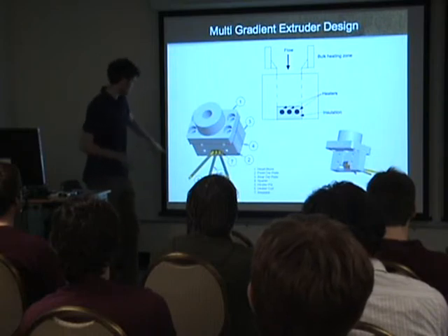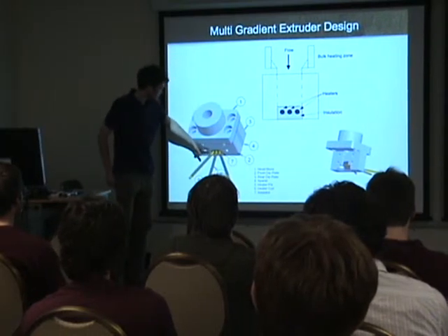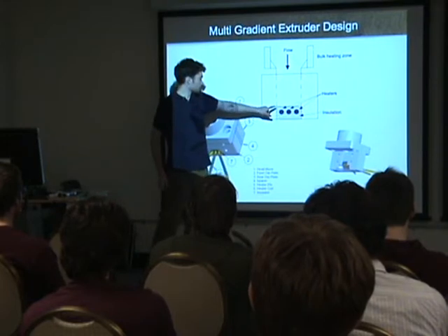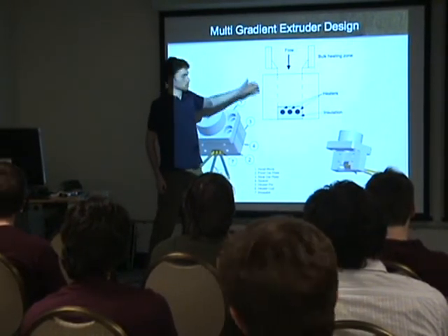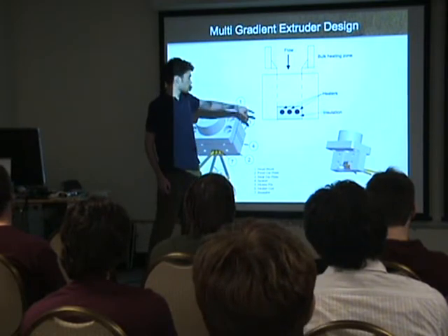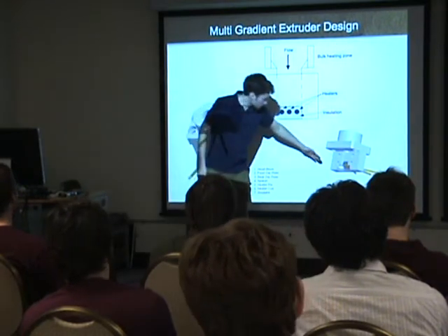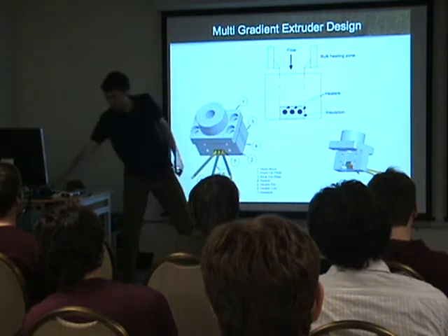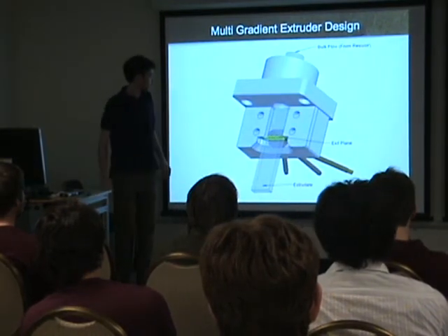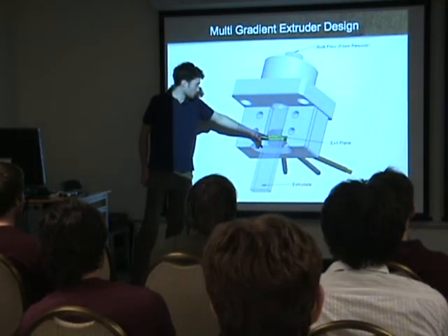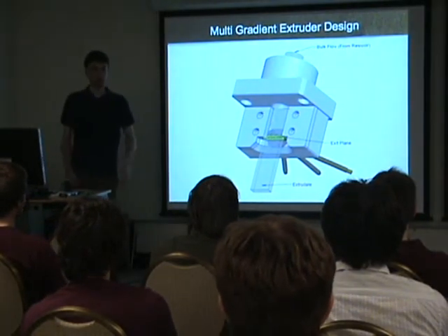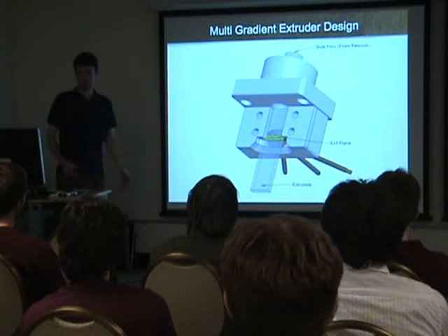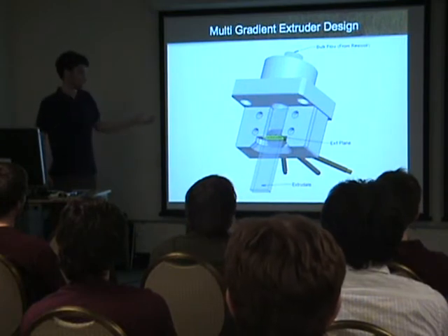You can see here these are brass heater pins separated by an insulator layer, in a main heater block which we can maintain at a temperature. If you look at this drawing, as this extrudate is coming out, the last surface in contact is this temperature-controlled pin. So right in these regions, we can control that surface texture and hopefully create some interesting designs, well, in this case letters, as our proof of concept.